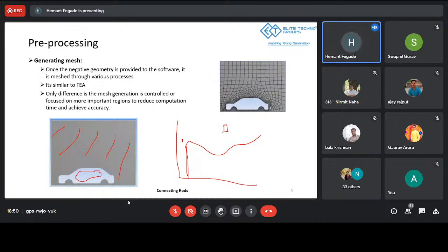So this is how you divide each and every part, and for each and every cell that you are seeing over here, you will calculate different parameters like velocity, pressure, temperature, kinematic viscosity. All these parameters you will evaluate, and will calculate turbulent energy dissipation. All these parameters will be calculated at different stages. Again, in order to optimize or understand this phenomena, what we as computational fluid dynamics engineers do is optimize the shapes. So basically we divide it in regions.